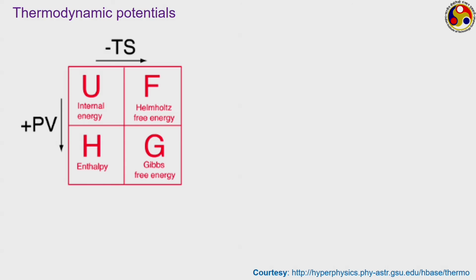Then what is enthalpy? We know to get enthalpy we have to add this PV with U. Here all symbols are shown in extensive sense; if we write in intensive sense, then we know that h is equal to u plus P into specific volume. So, with internal energy we have to add this flow work, and this flow work can be visualized as a work which you need to make some space for this particular system. So, enthalpy is representative of the amount of energy needed to create the system plus the amount of energy required to make some space for the system. This is enthalpy.